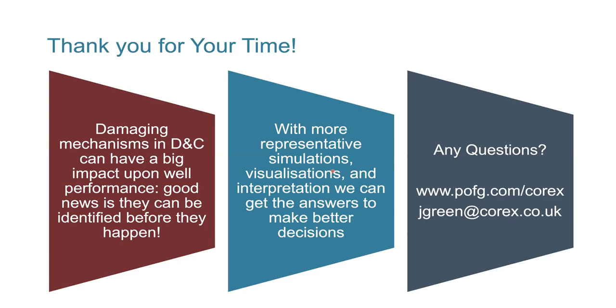And yes, in certain situations, laboratories will just do a static fluid loss cell. I should have said the kind of core holder and test rig that's used in high-tech lab testing is fully dynamic. So the lab data I showed you here with the filtrate loss was fully dynamic filtrate loss. So you absolutely have to capture that to get meaningful data, Abdulaziz.